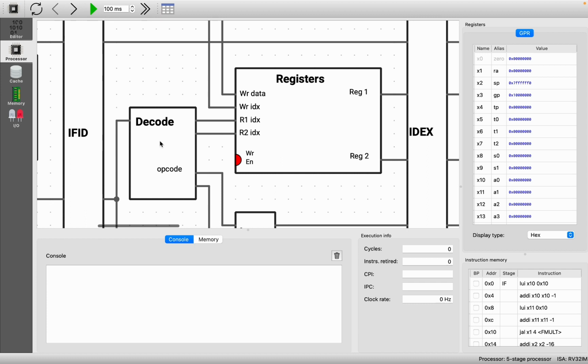And ideally, we wouldn't need to do any logic to determine those, right? If each control signal is a single bit, then ideally I would just have them correspond directly to bits in the instruction. And so any logic that we add that takes in bits of our instruction and converts that to bits of control signals is kind of a waste of resources.